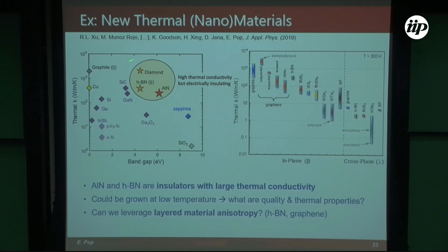It turns out if you want materials which are electrically insulating, but also thermally conductive, you have 3 choices right now. There's only 3 choices that I'm aware of: diamond, boron nitride, and aluminum nitride. Diamond is, as you know, very expensive. It's very difficult to grow. I have a colleague at Stanford who grows diamond, but it's not very high quality diamond, right? So she's obviously struggling with it, but it is what it is for now. But the boron nitride and aluminum nitride, especially aluminum nitride growth, actually is quite good these days. It was figured out by the people who got the Nobel Prize for the blue LED, you know. And so people have been growing aluminum nitride for many, many years. Boron nitride and diamond growth is not that good.